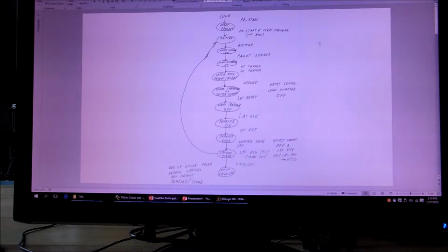I know Peggy says you've got to have some idea of what you're going to write before you start writing it. And with Factory I/O, you forcing on signals and then seeing what sensors go off and what actuators you need to do, it makes it really easy. So you should start out with something like this.